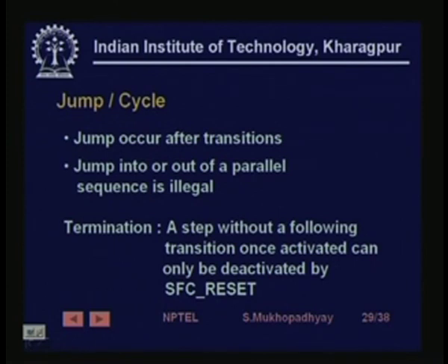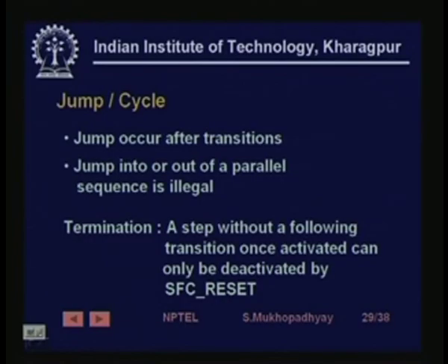Similarly, lastly, you may have termination of a program. So, a step without a following transition. If you have a step out of which there is no transition, then it is a dead state, and once it is activated, it can only be deactivated by a special instruction called SFC reset.